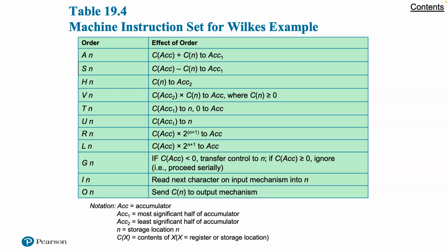Consider table 19.4. In addition to the use of control signals, each microoperation is described in symbolic notation. This notation looks suspiciously like a programming language. In fact, it is a language known as microprogramming language. Each line describes a set of microoperations occurring at one time and is known as a microinstruction.